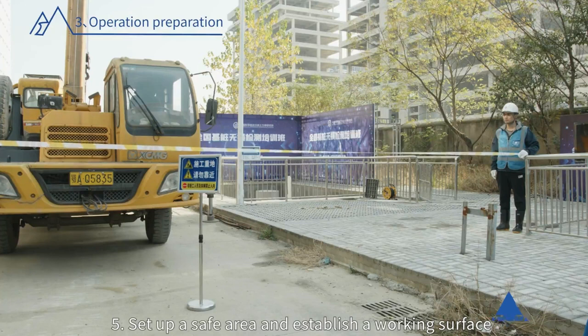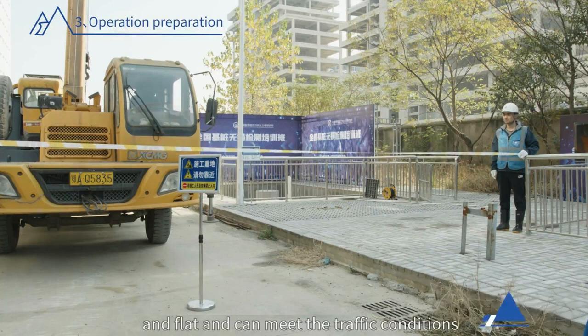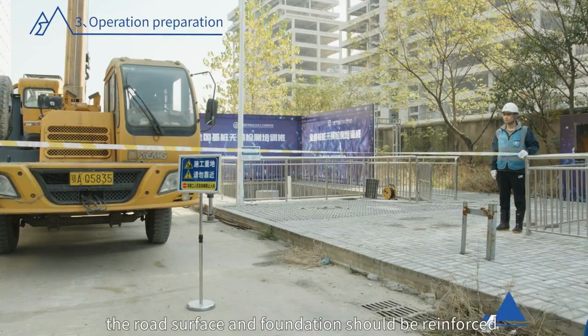5. Set up a safe area and establish a working surface. The testing site should be dry and flat and can meet the traffic conditions of large hoisting equipment and the requirements of hoisting operations. If necessary, the road surface and foundation should be reinforced.